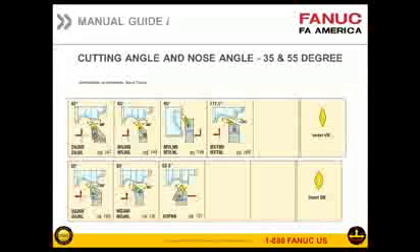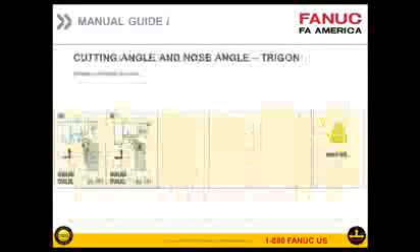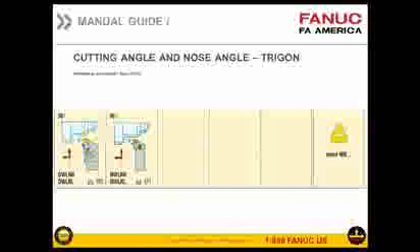Then the last one is a trigon, and again, it's like the 80 degree type insert, and it has 5 degrees of clearance, so it's going to be 95 degrees, and then you put 80 in the shape of the tool.